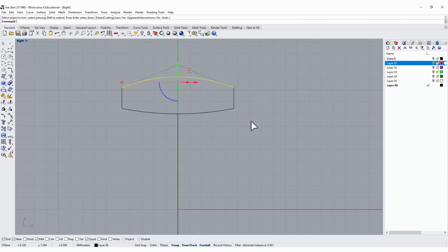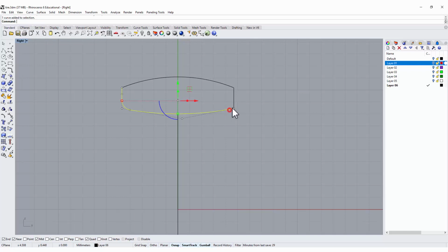Although the inside is already a comfort fit, it's not so comfortable at those angles. So I'm going to use the fillet curve and set it to 0.8. In my case, that rounds off the inside a little bit. On the top, I might also want to round it off as well. You can change the fillet radius to make whatever profile you want. Once you're done with everything, let's join it.